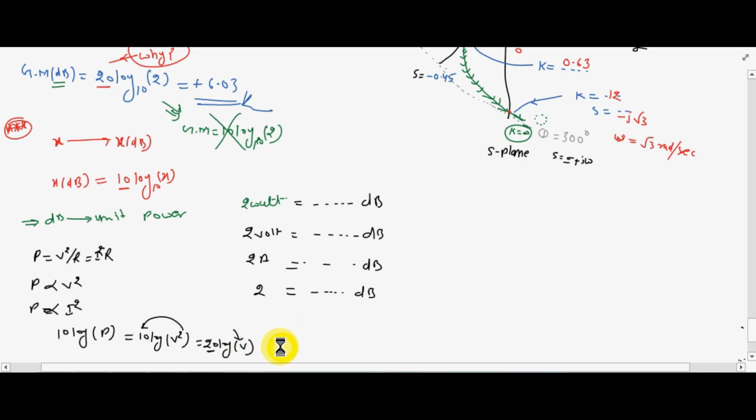Now, in our electronics, the voltage is V naught sine omega t. This is also voltage, or this is the amplitude of this signal. In our log, if this quantity is power, then we take 10. If that quantity is not a power, but voltage, current or amplitude, then we take 20 log x, by help of this derivation.